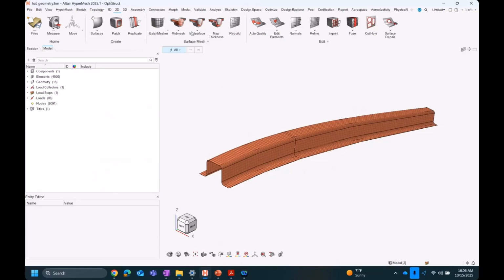Okay, so I've got HyperMesh here. I've got this hat model loaded, and I already have a mesh ready to go. I want to first show you how to create, from scratch, a few plies or a laminate within HyperMesh. But I'll really spend more time talking about the different import options: importing a CATIA model, a FiberSim model, and importing a spreadsheet to define your composite layups.